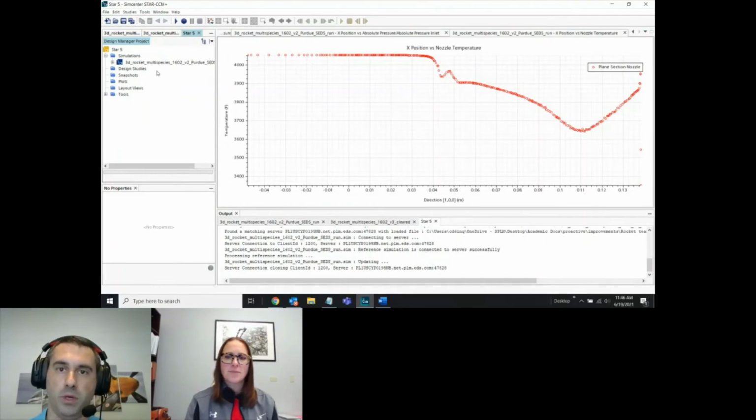In Star System Plus, when you tell it to use one core, it's going to use 100% of that core 100% of the time. So if you are doing emails and other things and you want to keep doing that while you're running a simulation, oftentimes what I'll do is I'll use 3 of my 4 cores and leave that little bit of headspace so that I can keep doing the rest of what I need to do. If I'm running a sim at night, I'll close down everything off my computer and then I'll let it run on all of my cores and I just won't mess with it. You can still do stuff on your computer. It's just, it might be a little bit slower.